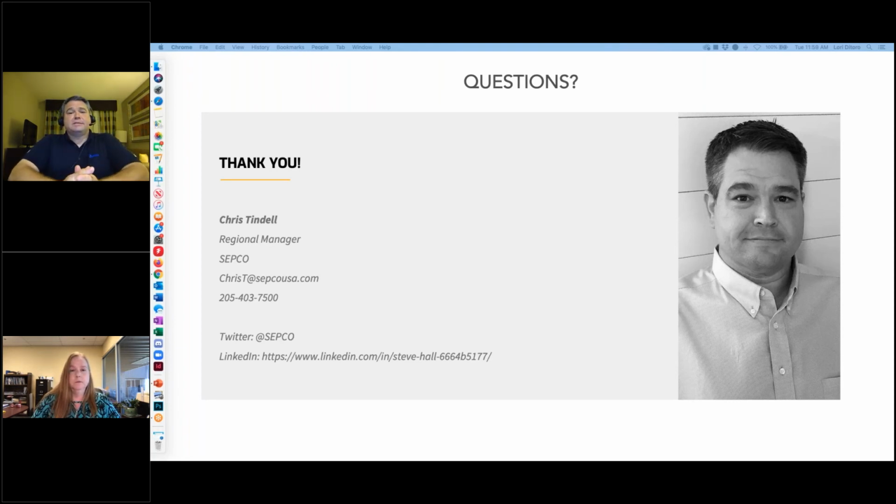They actually do. It's something that I think most people don't realize. We bring in lubricants, and it's just expected. The barrels that come in, the manufacturers would 100% agree that they need to be filtered prior to use. And they will filter it for you. I mean, there's a charge for that, but again, it's one of those storage and handling things. It's best to bring it in and do your own filtering, either into the top off container that you're about to use or into the machine.